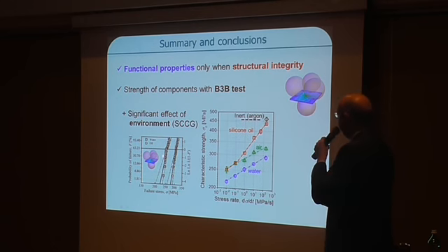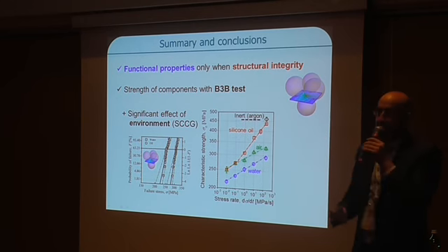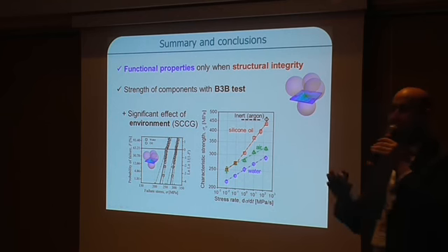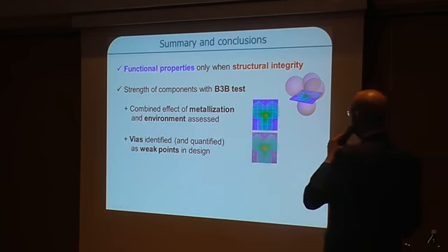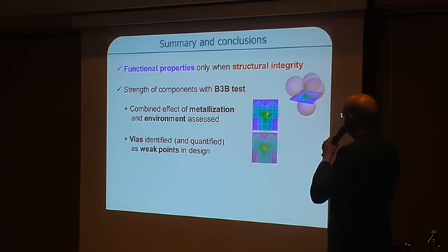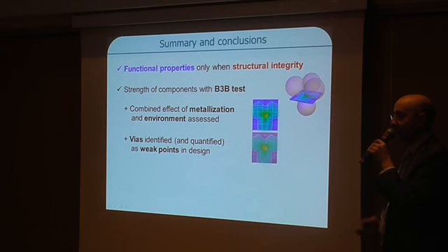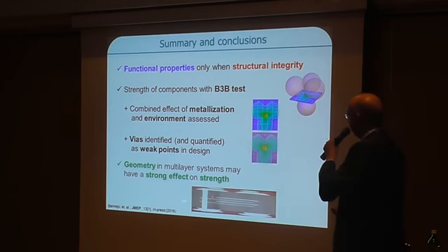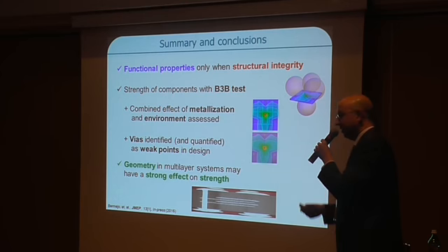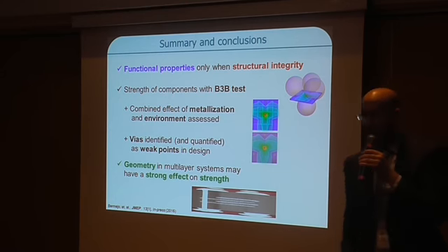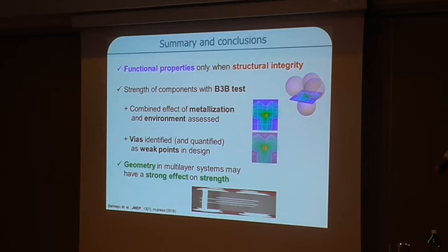characterization. We can see effects of environment that with other testing methods could be very difficult to discern between small differences, let's say. It is interesting that you can check what is the effect of different patterns, different metallizations, combined effects of structure, architecture, and environment. And for the example of real components, we could also see that just a simple difference in geometry could have dramatic meaning for the lifetime.